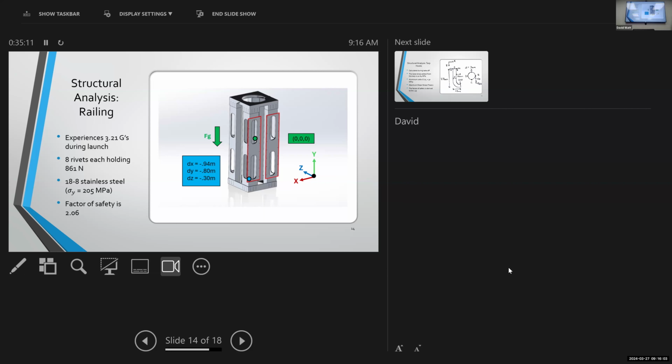The load that my structure is actually going to see in service, the 99.9 percentile environment, if you've got any sort of random variables in there, is say 500 pounds, right? So I've got a 1,000-pound allowable, I've got a 500-pound design load, and then I've got a 1.5 factor of safety, right? So I'm going to take 1,000 divided by 1.5 times 500, right?